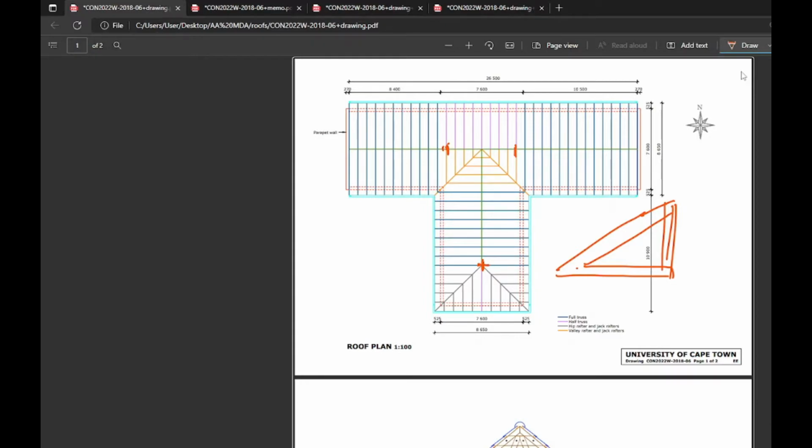We haven't accounted for fixing this end onto the main roof structure. So this end onto this roof structure is not accounted for, and I think the same goes for whatever happens at the bottom, the tie beams. What are we attaching our half tie beams to come across? We have not taken them. And as I said previously, I'm not sure if there's anything down here. It could just be open space. Oh, my word. Okay.